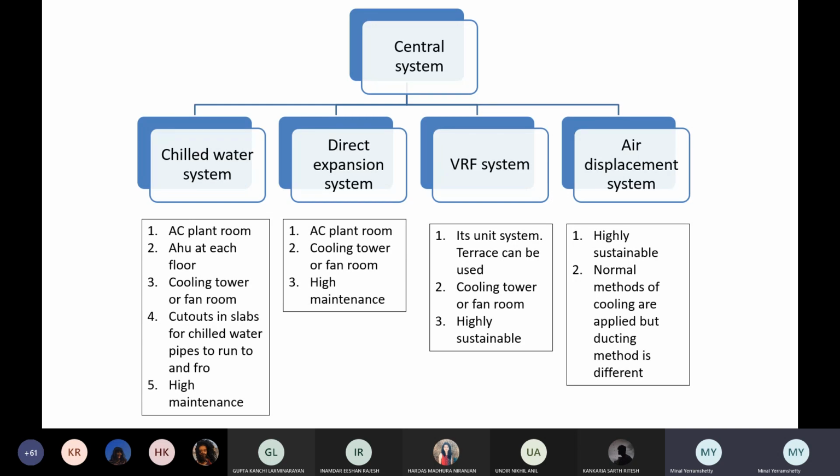Now again, just as a precaution, and since we have already done high rise, if you have to take a very long pipe, say in Burj Khalifa, it's not possible. We don't carry water that far, so how will we carry chilled water? So in that case, your building is definitely zoned. What happens at the basement and at the terrace level will happen at every mechanical floor. Every mechanical floor will have to think of a way to put the cooling tower where it is exposed. That is how your high-rise buildings will function.